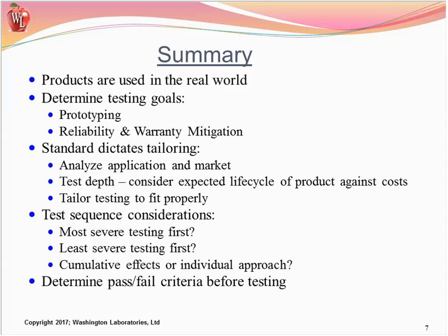So hobby batteries are not necessarily so benign, and assembled packages, the package that would fit the drone by the manufacturer. But remember, don't assemble your own pack from cells without analyzing the requirements for the integration of a pack, because suddenly you've assembled something that has higher voltage, higher current capability, depending on how you've arranged them, more longevity, etc. So by that token, if you self-assemble a battery, you need to get the approvals for a battery requirement.